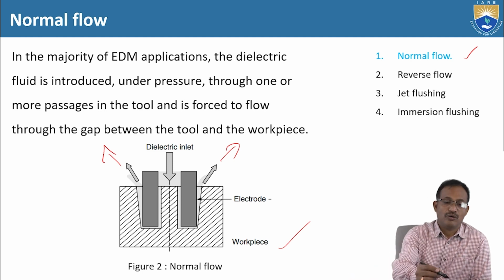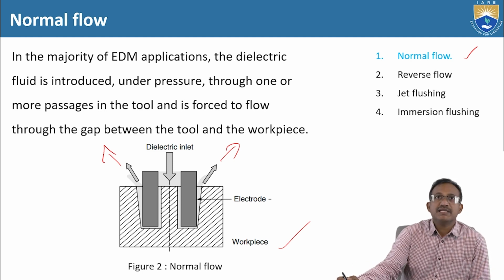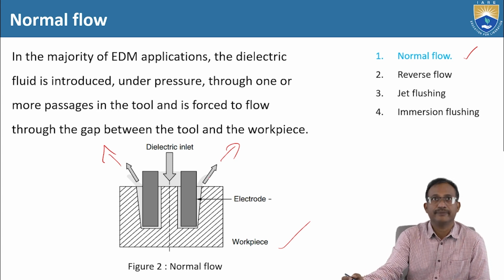Now, in the majority of EDM applications, the dielectric fluid is introduced under pressure through one or more passages in the tool and is forced to flow through the gap between the tool and the workpiece. So that's what we have discussed already.